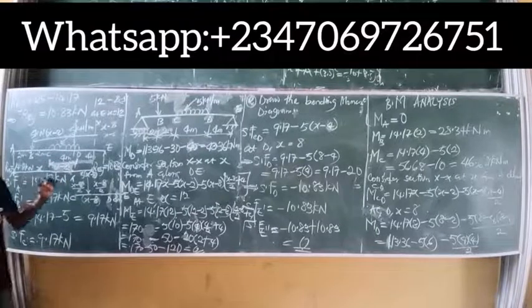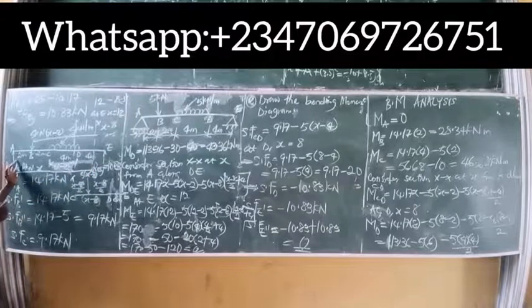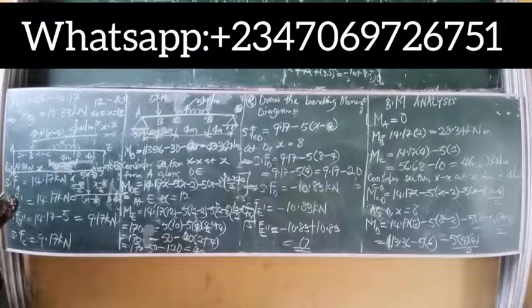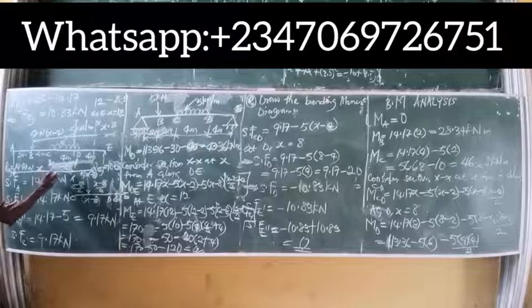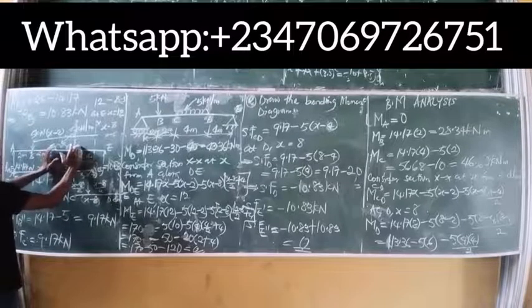And eventually I know I'll get to point A. And for that reason, if here is 2 and here is 2, here is 4, 2 plus 2 plus 4 simply gives me 8, right? So to get the length of the UDL, simply take away that 8 from X, because I only need from C to D. That's my second shortcut. I only need from C to D.